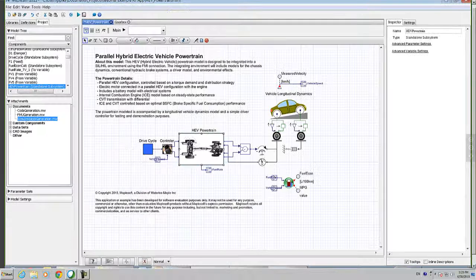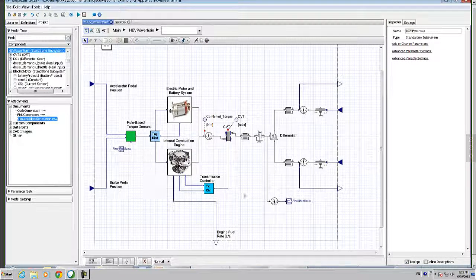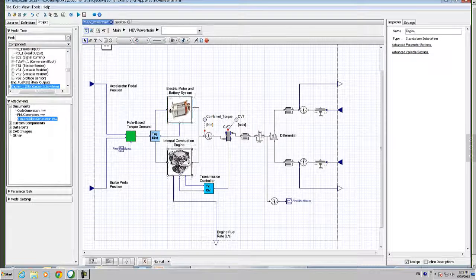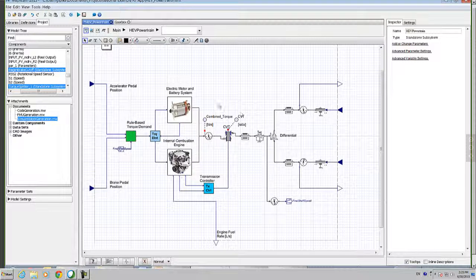And so you can see how we can develop our subsystem, and all we need to do is specify our IOs. Within the subsystem, the MapleSim model can include multi-domain system modeling, from the electrical to mechanical, overall control structure, and relate the physics of what's happening in the powertrain out to the driven wheels that are connected as the output side, and how the driver model will be connecting with the accelerator pedal and brake information to control the overall powertrain.